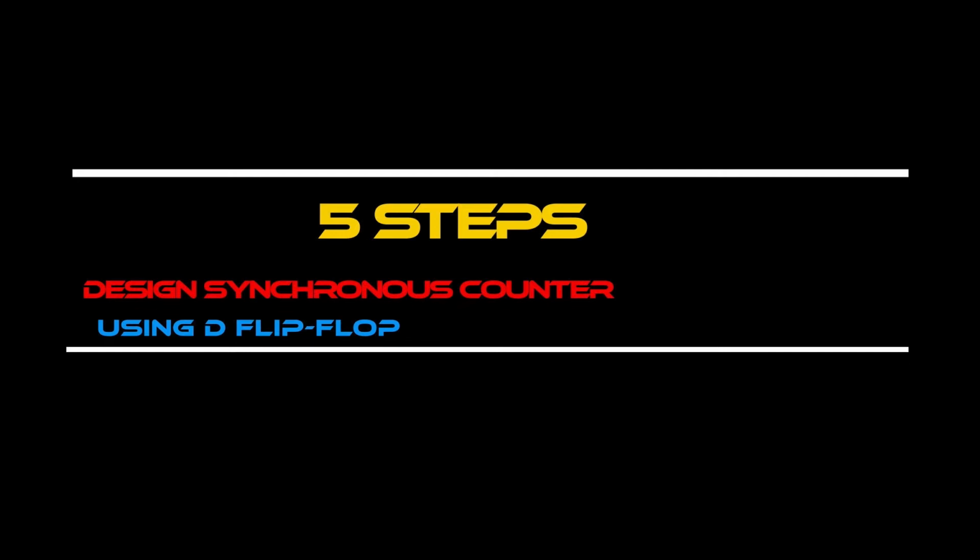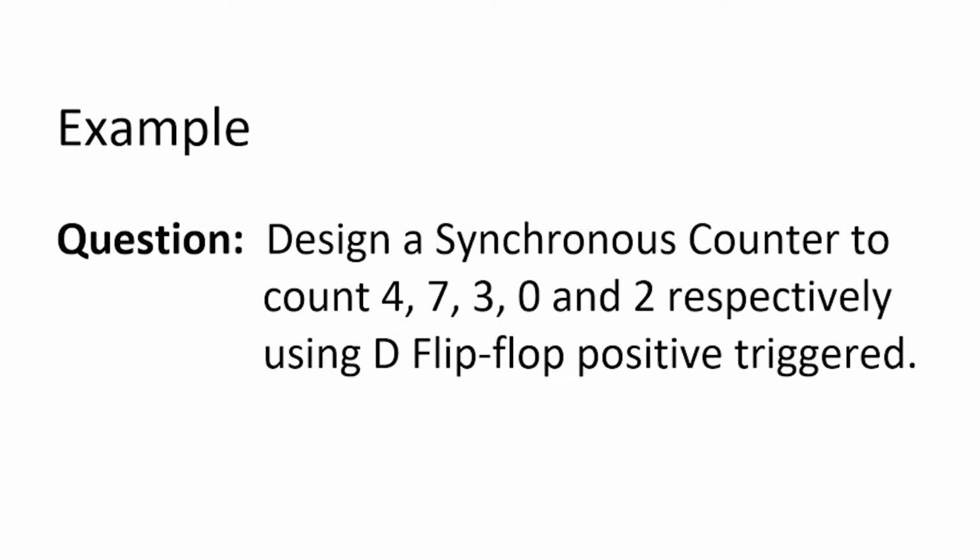The easy way to design synchronous counter with one condition. Just follow 5-step design. Let's say I give one example. Design a synchronous counter to count number 4, 7, 3, 0 and 2 respectively using D flip-flop with positive edge trigger.